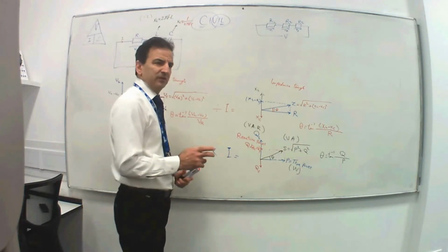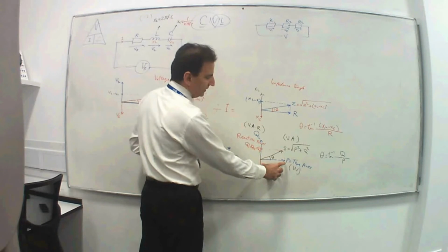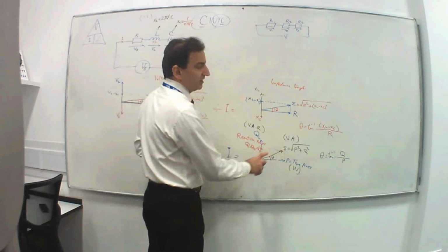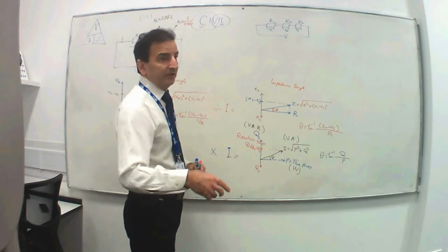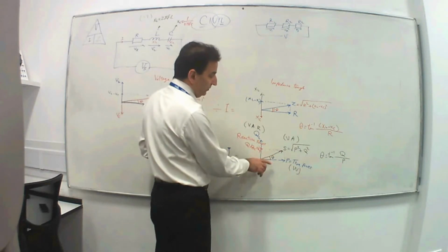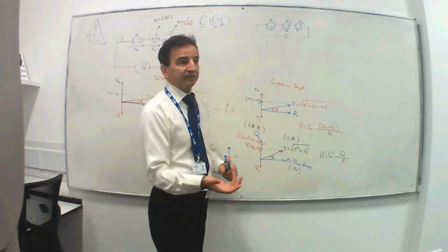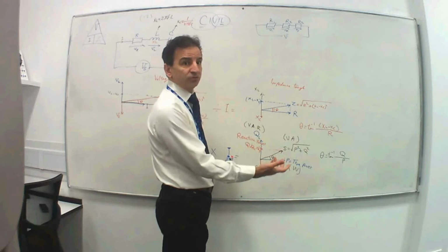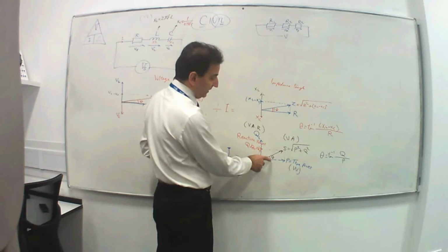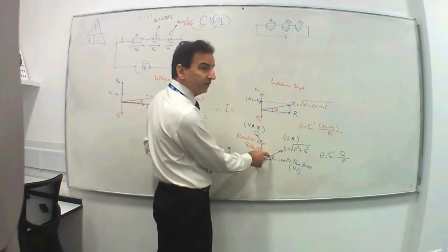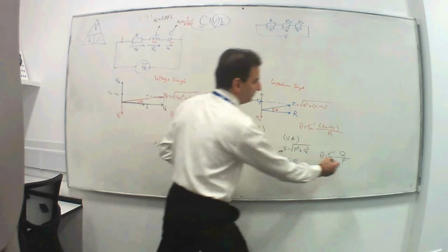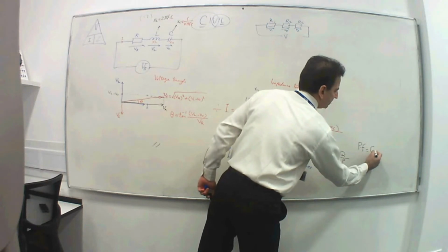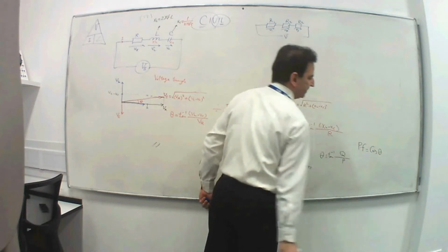And we talked about power factor briefly. We said basically true power is how much you use, apparent power is how much you pay. To bring this down is called power factor correction, so you're trying to correct it, so you pay as much as you use. The cos of this angle is your power factor.